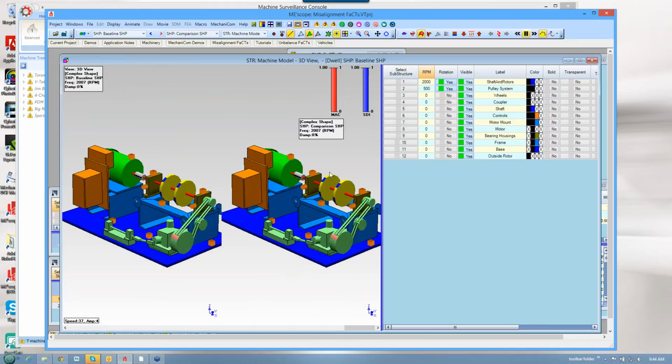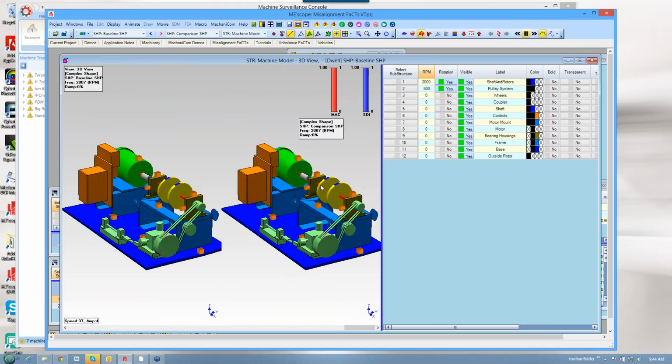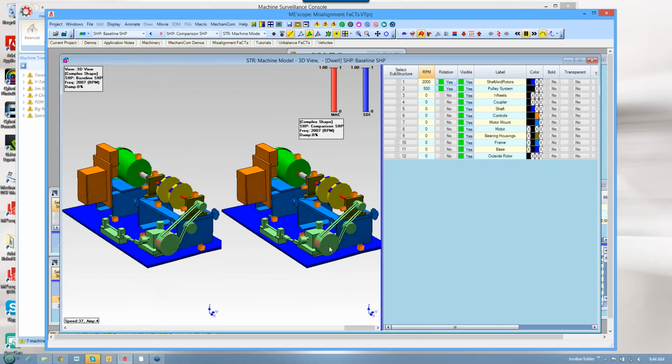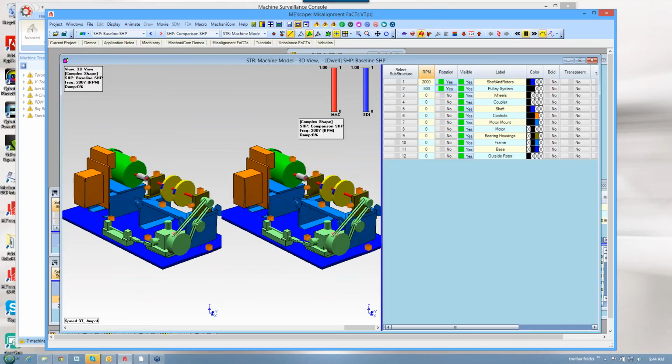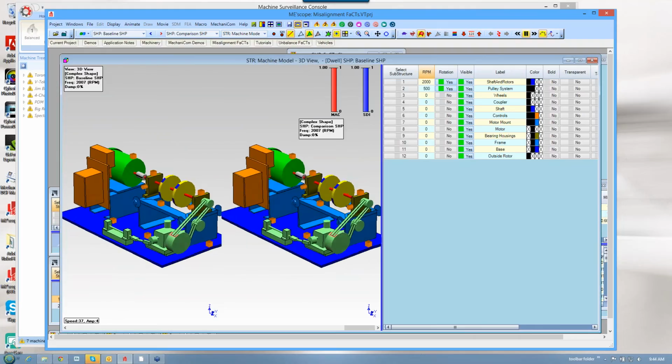You can see that here, that the shaft is rotating at the speed of the machine, and then the belt is rotating, or this pulley down here is going more slowly. So the macro is setting those speeds in there based on which order I want to look at, so that I can compare the vibration at that RPM to the rotation of the machine at that RPM. So let's go back here and look at, so that's what this is doing.